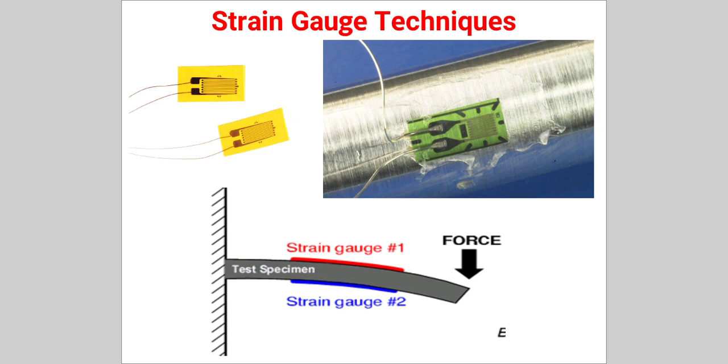in water applications. As we go through the figure, the first figure shows the basic construction of the strain gauge. The yellowish part represents the backing material, also called thin paper, and the element at the center is called the grid element or the sensitive element, whose resistance will change. While pasting the strain gauge on the specimen, there should not be direct contact between the sensitive element and the test specimen. If there is direct contact, the resistance will change immediately and it creates an error during the measurement.